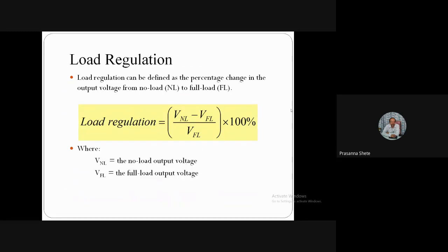Similarly, we will calculate load regulation where we have two important parameters VNL and VFL. That is VNL is no load voltage and VFL is full load voltage. And the definition of load regulation, my dear students, is given as VNL minus VFL upon VFL into 100. It is given in percentage.